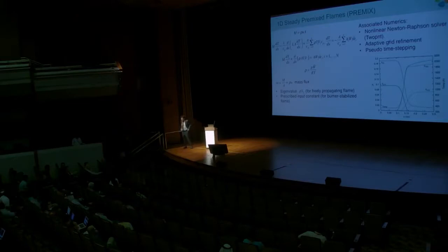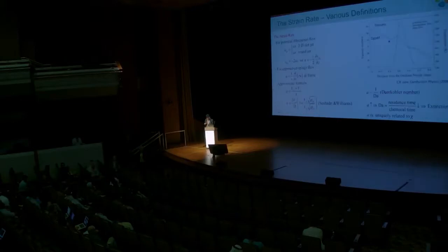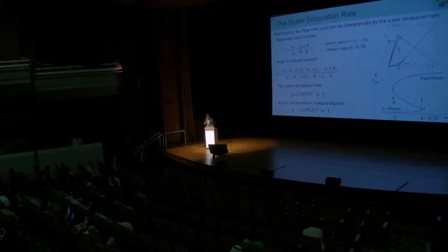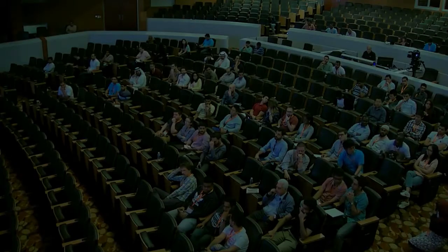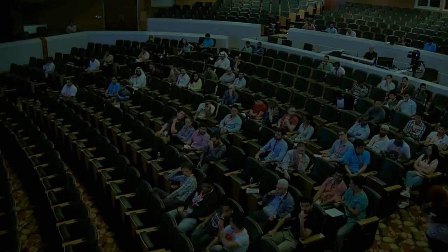Please. Yeah. Thank you, sir, for an excellent presentation. I have just one simple question about the mixture fraction. If one has a system where there is flue gas recirculation with some carbon dioxide in it, how does one track the mixture fraction in the reaction zone or in the combustion region when there may be CO2 that recirculates and maybe participates in the reaction?